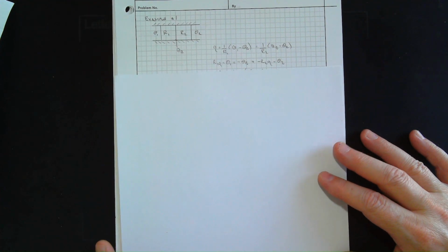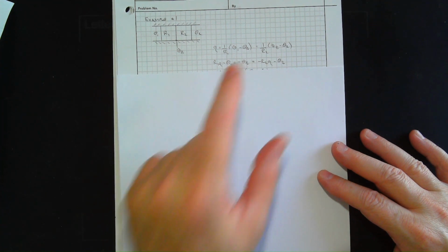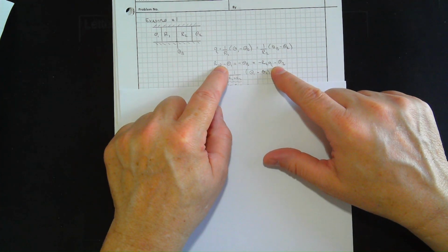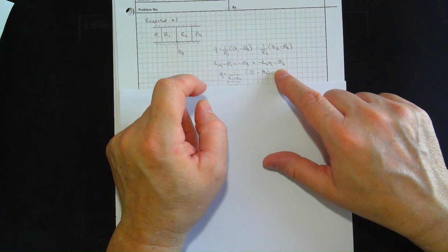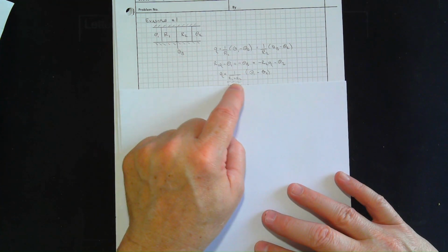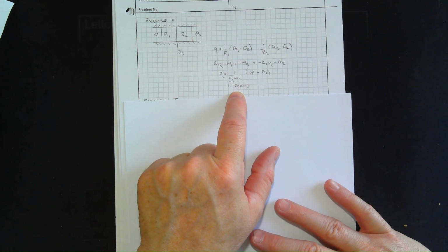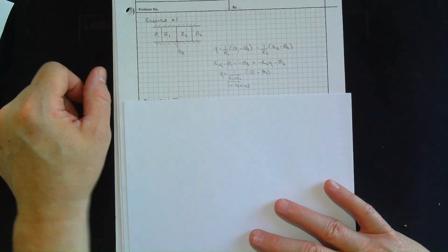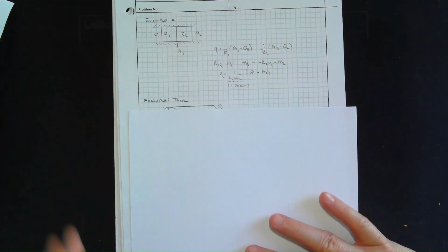All right. Well, now looking at this, this must equal that. We have our minus theta B in the middle, and so we'll just equate these two on the outside. So we can bring the R's to the other side, bring the theta to the other side. And we wind up with the heat flow is equal to 1 on R1 plus R2, times theta 1 minus theta 2. So they're in series, they add. Well, that's kind of what we'd expect, right? As an electrical analog, resistors in series add. This is thermal resistors, that is.